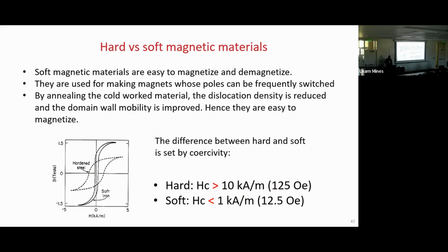Soft magnets in a motor, this is the interesting part. You keep mentioning that you can use an induction motor. The difference between an induction motor and a permanent magnet motor is about 10% efficiency. And that 10% efficiency, translated into battery cost, is actually way more than whatever the magnet costs. Even if you pay $250 per kilogram of magnet, you're still saving money. This is why Tesla decided to use the permanent magnet motor about 5 to 6 years ago. Someone one night said, okay, my Model 3 can run 10% longer, from 240 to 300 miles.